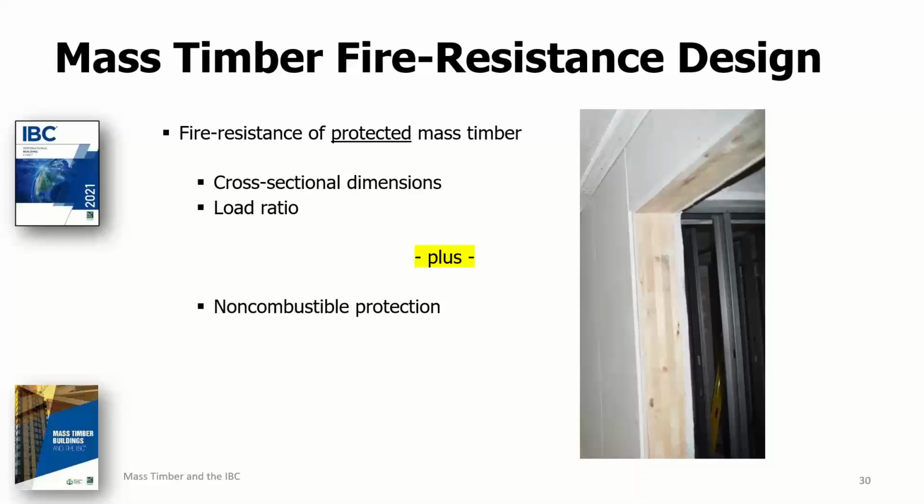It's one of the characteristics that distinguishes the fire design of wood from that of other construction materials. For wood, you can rely on a calculated amount of inherent fire resistance from the member itself, and then, if necessary, add to that any additional amount of protection that may be prescriptively required or necessary to achieve a particular fire resistance rating.